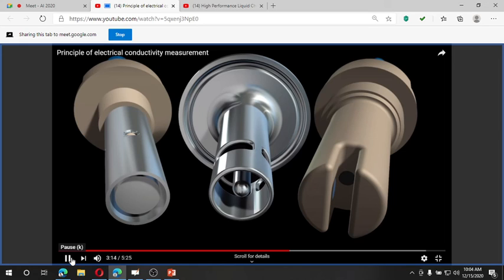You have something called the wall effect. It varies. Suppose you use a metal plate, that will also contribute to conduction. So you have to see what is optimal, and all these are taken into account. They use a constant called the cell factor, which accounts for the geometry and the distance between the two electrodes, depending on the electrode design, and influences their suitability for different areas of application.